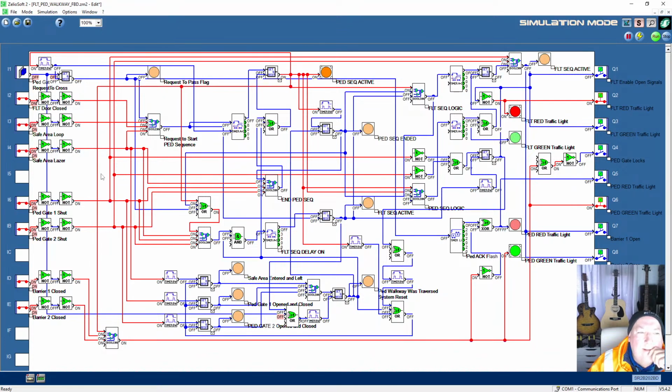If someone presses it, they need to go through the sequence. They need to have an overriding timer to complete the sequence. If the sequence never gets completed, what happens if you trigger that? You get an impulse and it starts counting down again, but it's already in this mode. So it's still going to wait for the gates to be opened and gone through.